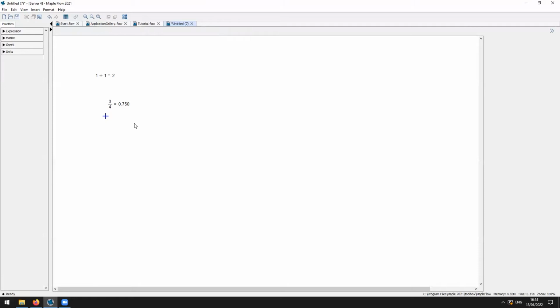So we have a couple of math containers on screen, and we can move them about. If I take my mouse and left click on this math container, I can shift it about on my canvas, like so. There's another way of moving math containers about on screen, and this is the method I use. It's a keyboard shortcut.